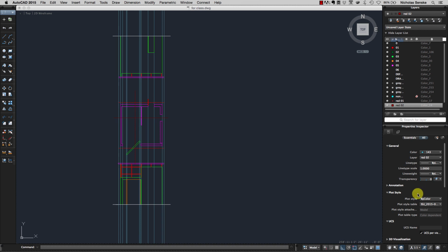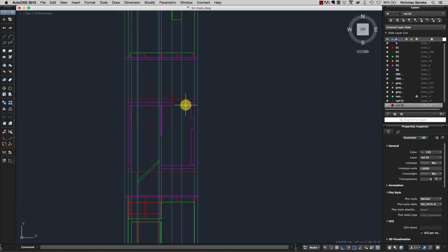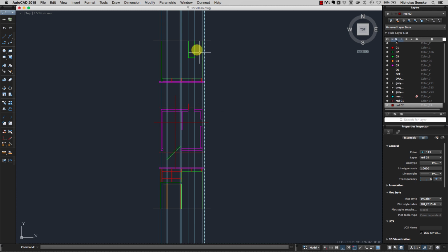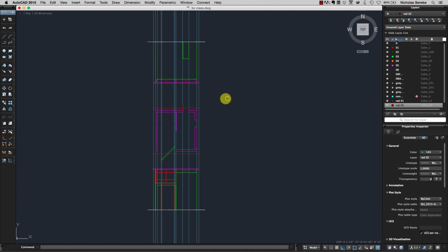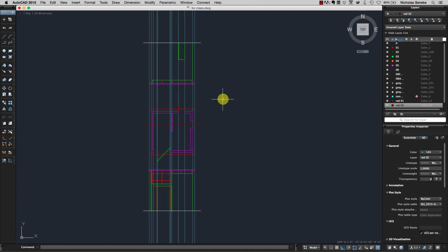We're talking about how to draw a section from a set of orthographic plans. And if you look at the drawing here, you can see where we left off. So we got a plan that we drew. We've got our section lines here, and we've got the elevations that we projected off of this plan, and these are the construction lines. So what we're going to do is organize a drawing so that we can generate our section drawing.